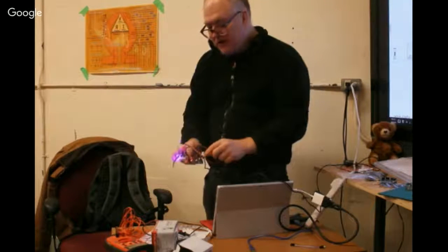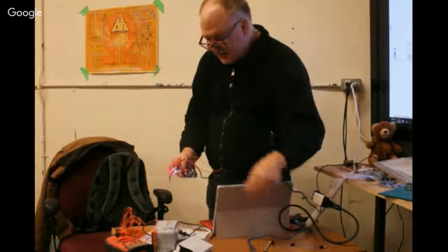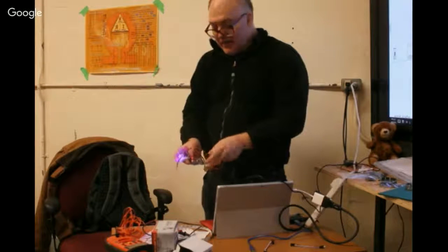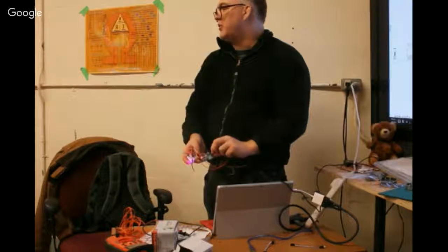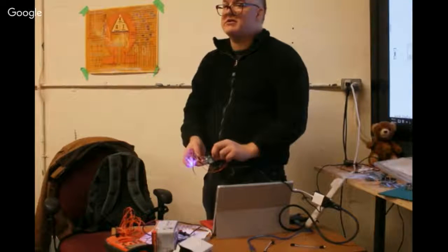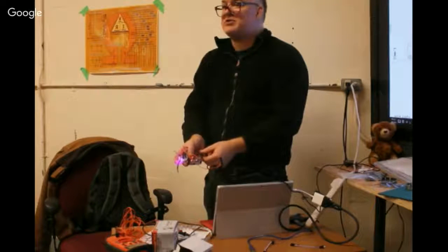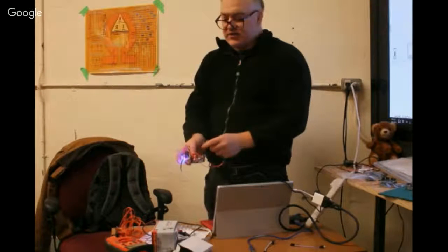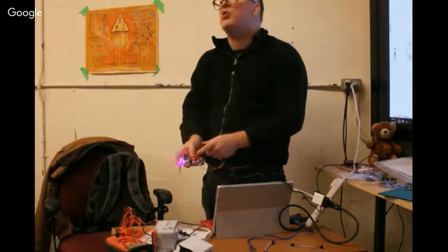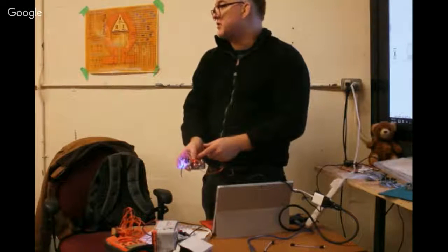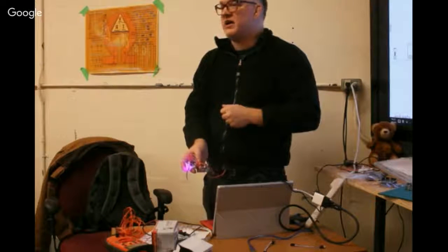There's a pin called VIN on the Arduino board, though, that's right at the base of the power pins on the same side as the power supply there. And that VIN is actually exposing the supply voltage of the Arduino. Now, one thing to keep in mind is that if you're plugged into the 12-volt supply, that's great. That's what you'll see on the VIN pin. If you're instead plugged into the USB port, driving this off the computer like we have been so far, you won't see 12 volts there. You'll see only 5 volts there because that's what the USB supplies. And that's actually the base required power for the Arduino, that 5 volts.